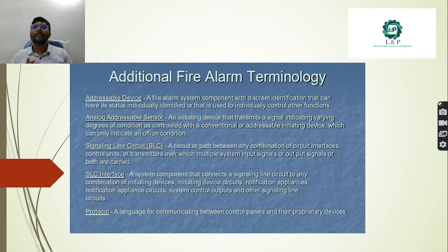For example, this analog threshold value you can keep at minimum for small errors or troubles which are occurring owing to dust. But for the critical errors, you can set the threshold limit to high. If the analog value is greater than the threshold limit, it will create an alarm. Like that you can configure the analog addressing devices.